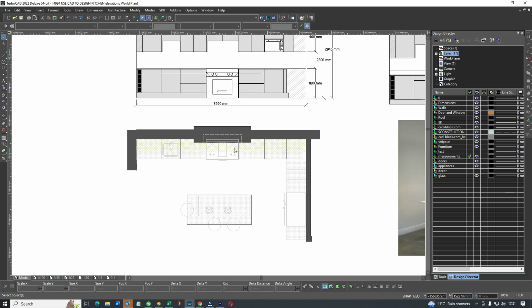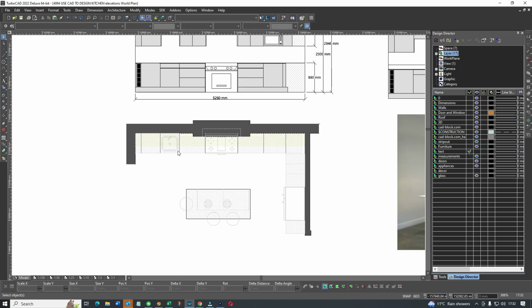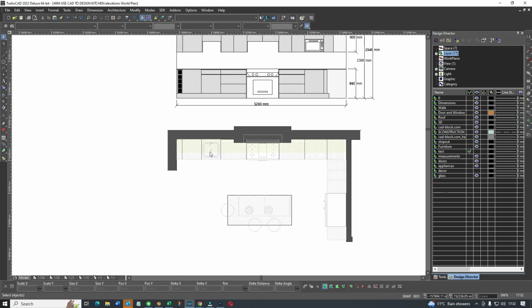Occasionally it's a bit of a challenge because here we've got a chimney breast in the middle which we want to integrate into the kitchen design. The client has a big 1000mm stove, so we've got to get that central, but we also have to have the corner unit. So what we have here is the units, all laid out as base and wall units.